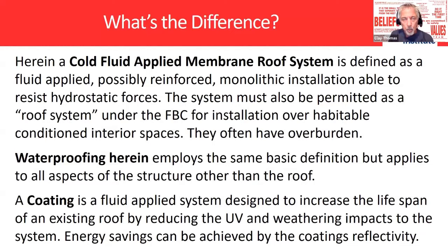We're also looking at systems that can be permitted as a roof system under the Florida Building Code. Now, what I found out in the past, because I work in a lot of places, and Mike, I'd like you to comment on this as we go forward, is that different areas of the state have different requirements. In South Florida, when doing a coating system, I need to hand in moisture surveys done by a third party, a lab, for instance, to the building department.